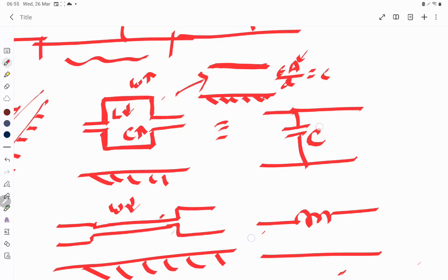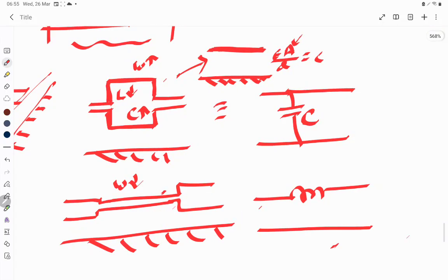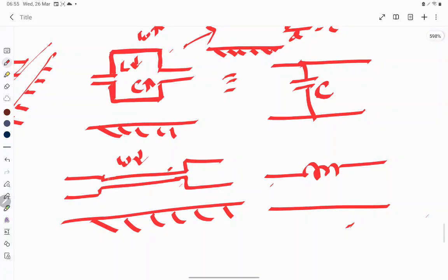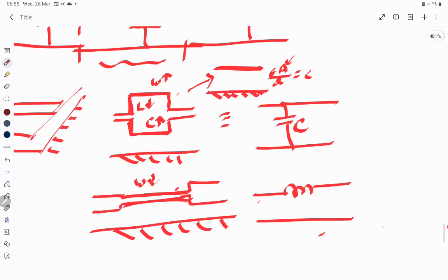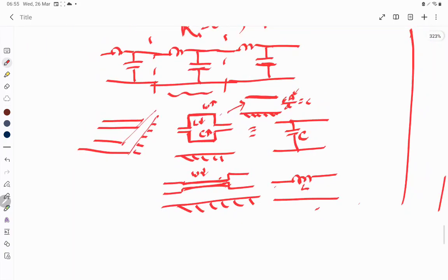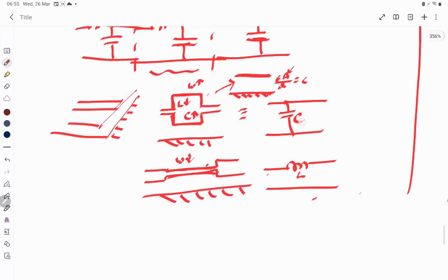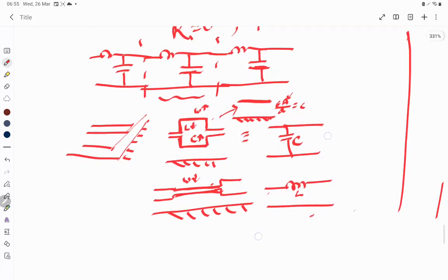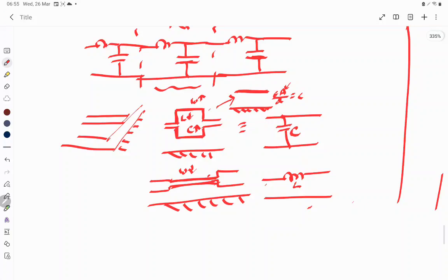Along with that, it will also decrease your inductance. Here we have increased the inductance value, and obviously your capacitance is now very small, so it can be ignored. Then it gives you a series inductance. Thus, we can utilize our distributed parameters from our distributed model, and use this nature to create a shunt capacitor and a series inductor.